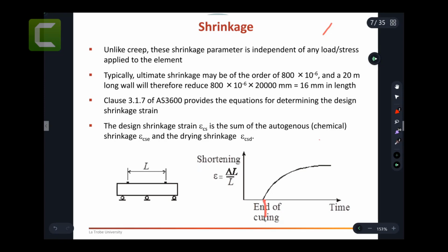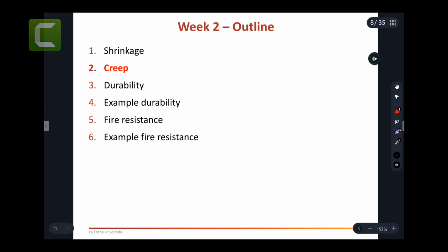Then from the day curing is ended, which is about 1 week or 2 weeks, that's from where shrinkage is actually going to start, because there's still going to be some extra moisture inside the concrete, and that's where shrinkage will happen. However, if you have the correct quantities of crack control, things will stay intact, and those obvious cracks will typically be prevented. All right, if we're talking about a slab on the ground, you can also introduce saw cuts, where you cut the slab at the upper part only of the section, or where you've got a suspended slab, you will introduce movement joints.